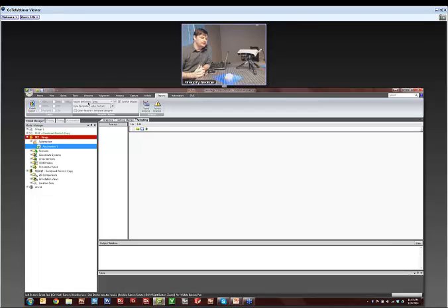Yeah, it can be used outdoors, although there's going to be some light that's within the spectrum of what the sensors are going to be looking for. So ideally, you try to reduce the amount of light that can throw off the measurements of the part. If you were outside, I would definitely try to put a shade of some sort over it. It just helps increase your measurement accuracy. As far as indoors, we measure all the time with regular incandescent or fluorescent bulbs, and it's perfectly fine. But as far as the device itself, it can be outside.